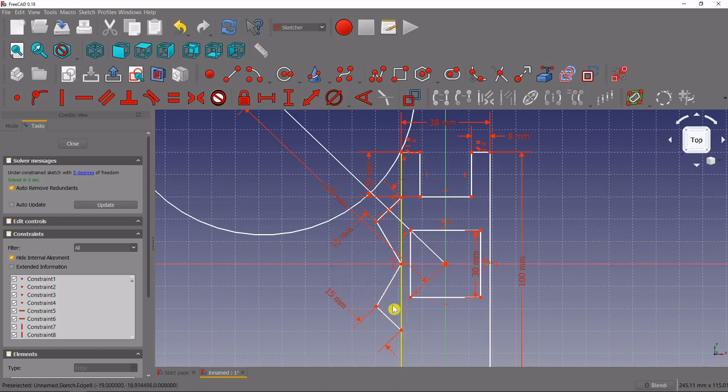We still have to add some of the other constraints here, and if we just play with this line a little, we can see that it looks like we need to fix the length of this. We need to put this on this line, so we'll fix onto point with that point and the edge of our frame. And then we need to click these two points here and give them a coincident constraint. And then we need to dimension the length of this line. So we'll make these two lines equal. And then it looks like the last point is to position this point here.